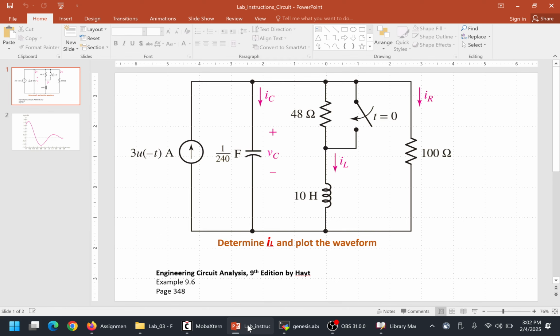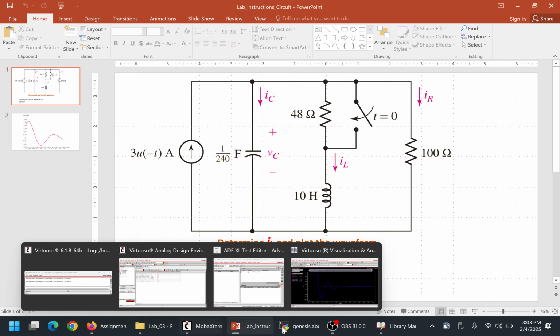It will have some transient response, and then with time, the inductor and capacitor will lose all the energy in the resistors and it will settle down to 0. That's a normal RLC behavior with no power source. The power source was there, but it turned off when the real function started. And this is exactly what we see in our plots.